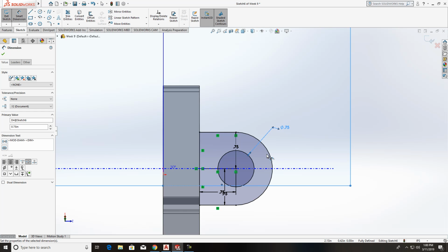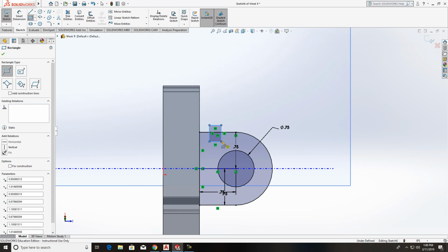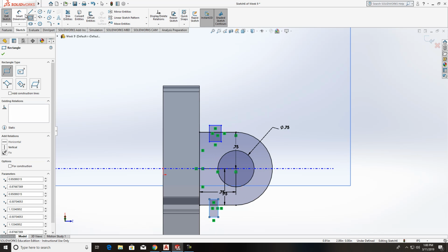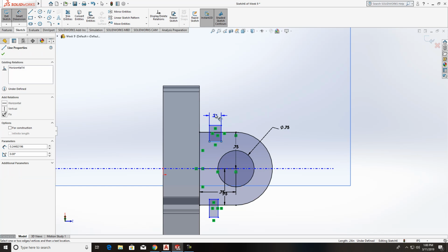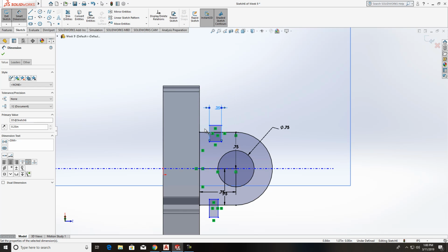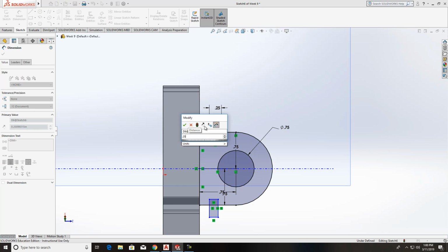Then it's got like little quarter inch, looks like little guideways or keyways. So we'll just come in here at that point, and I'm just going to put little rectangles in here and just adjust them where they need to be. That'd be fine. So smart dimension, this would be 0.25. Good. Smart dimension from here to there, 0.25, just like that.